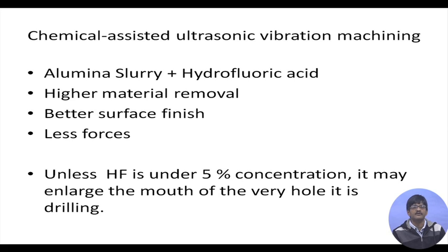So, when hydrofluoric acid is added, higher material removal is obtained, better surface finish is obtained, and the forces between the workpiece and the vibrating horn also come down drastically. However, if the concentration of HF is more than 5%, it may result in enlargement of the entry point of the hole which is being drilled, and therefore, concentration has to be kept within limits.